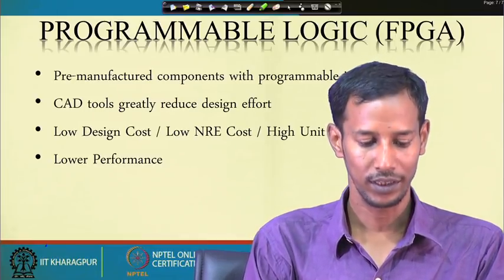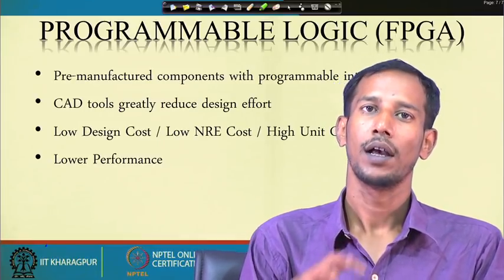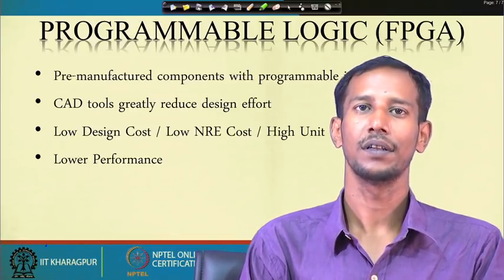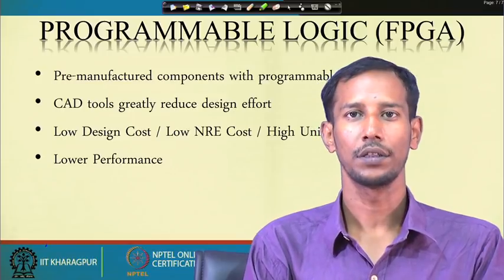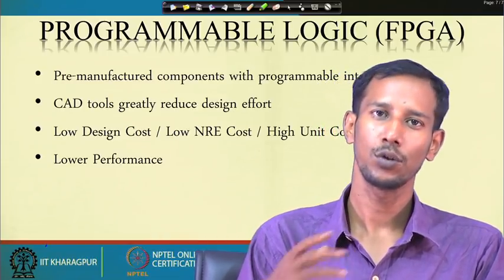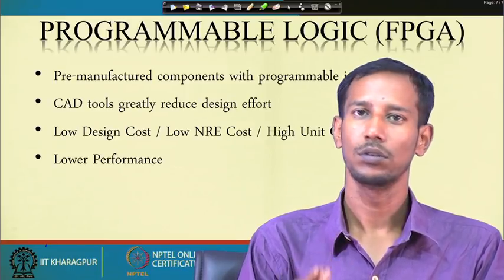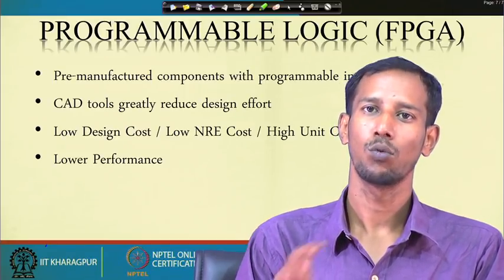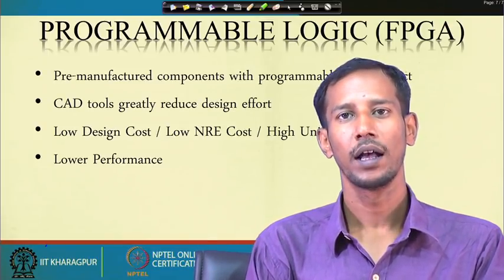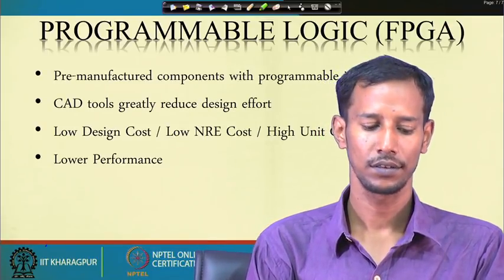So, that is why programmable logic is a better choice in the initial design phase. That means to validate your algorithm and your architecture, you use programmable logic. Once everything is fixed, then you can go for full custom or semi-custom design styles.